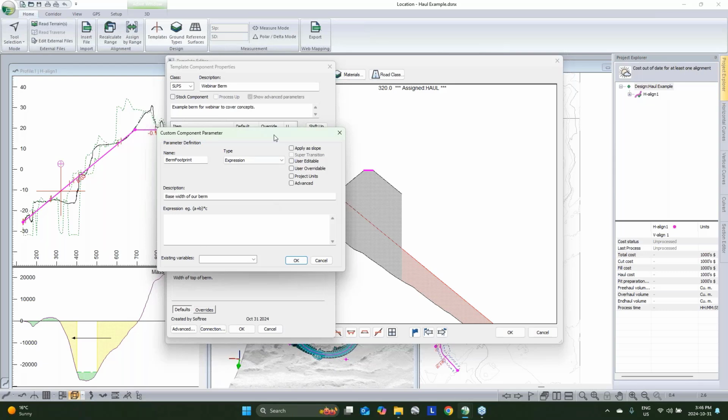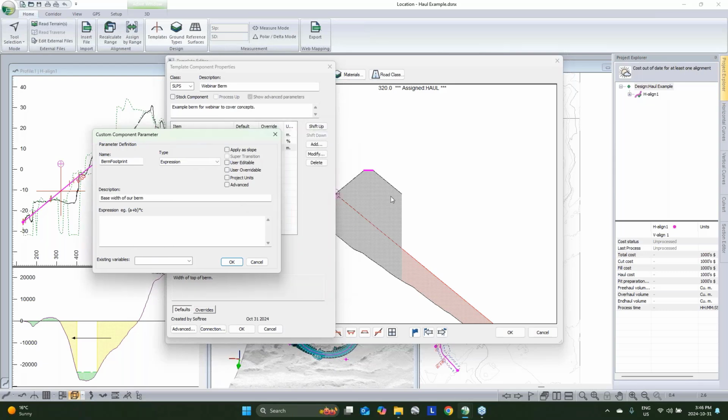So with this, how wide is that base? Well, we know our height of our berm, and we know the slope, so we can calculate how far out we go from that attachment point to our, I guess the foreslope of our berm. So I'll go berm height, and I'm going to just copy and paste that over here, divided by my berm slope.